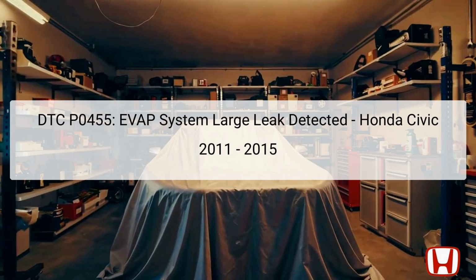When diagnosing this error code, several steps must be followed, including checking fuel fill cap installation, seals, and conducting functionality tests with specialized equipment such as the Honda Diagnostic System, HDS. Precautionary measures should be taken to avoid excessive pressure or vacuum during testing, as these can damage sensitive EVAP components.